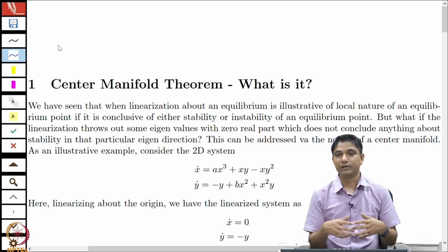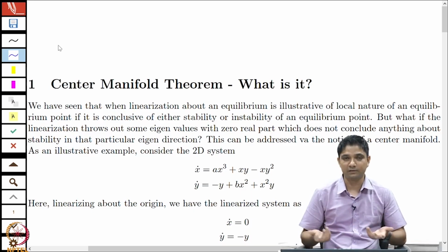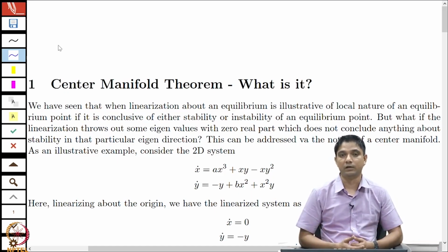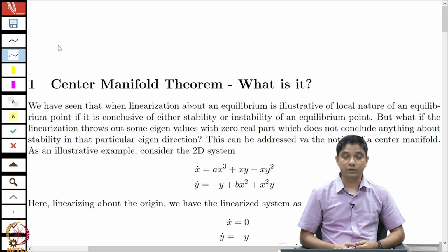So, we talked about linearization, we talked about defining explicit Lyapunov functions, and we had some methods to derive Lyapunov functions, especially the basic ones like an energy function or a quadratic Lyapunov function. Then we had LaSalle's invariance principle, and a few converse theorems about Lyapunov stability for nonlinear systems.